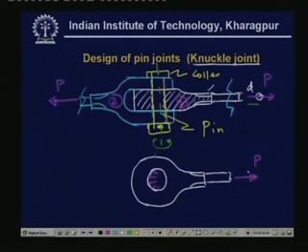Now first of all, once we see this, obviously the material may also fail in tear. It may so happen that it fails by breaking from this. So we have to now design these diameters, etcetera. If this thickness is T, let us say this much is T. The inner diameter is D1, and let us take this as D2.